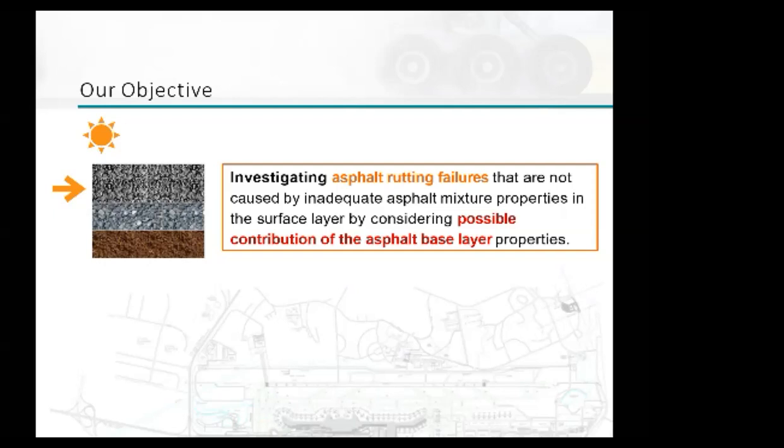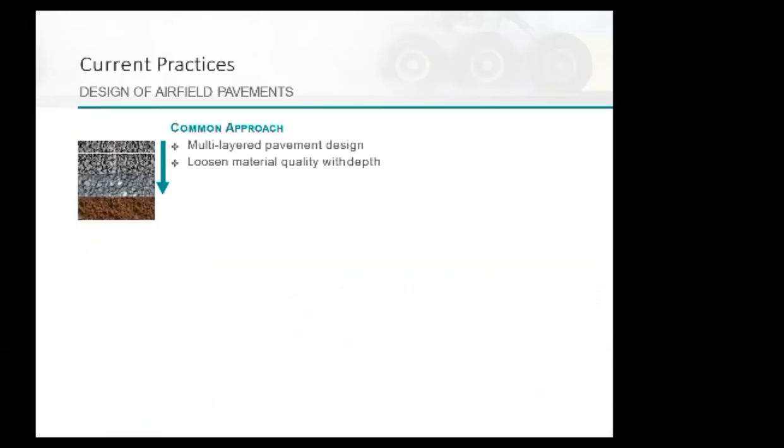That's the objective of the story I'm telling you now: to explore what is going on in the asphalt in the intermediate layer or base layer. What load is it feeling? How long is it feeling that load for? What's the temperature of that intermediate layer? Do these conditions really necessitate grade bumping or not? That's the motivation behind this work.